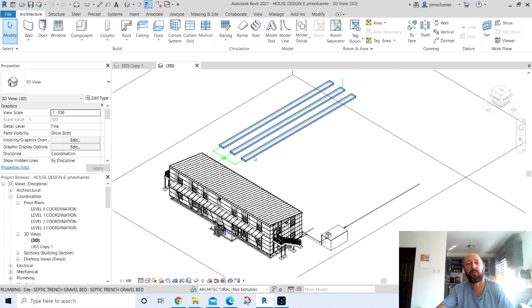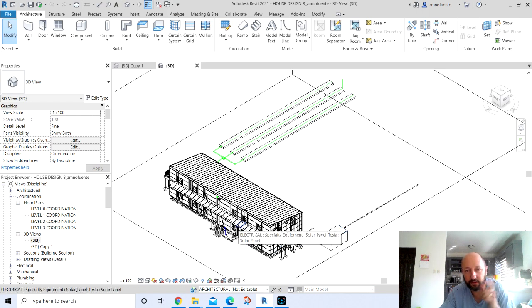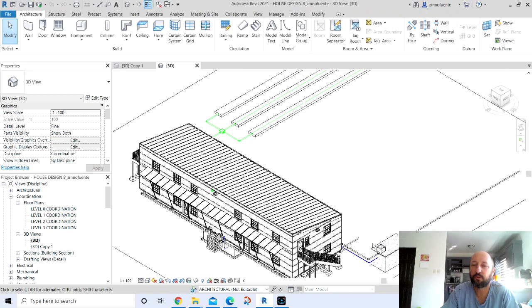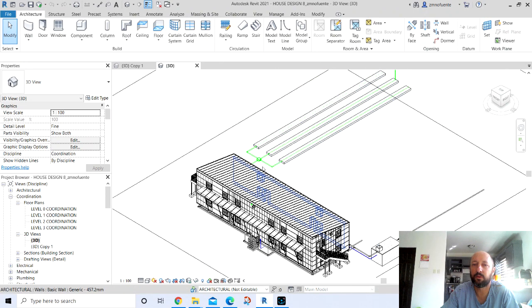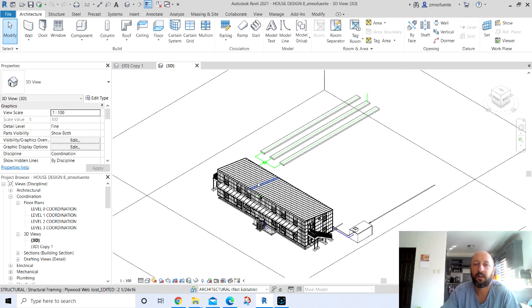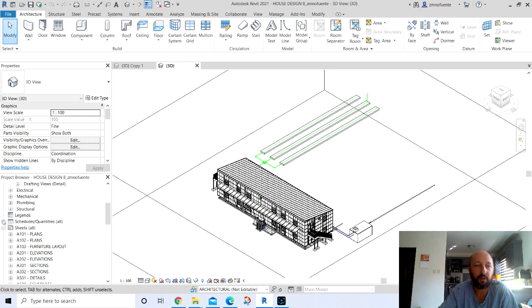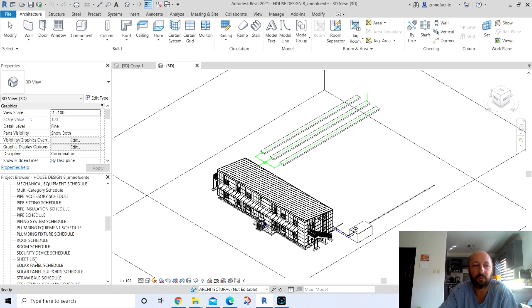Okay, so what I've got up here now is the Revit model. I used Autodesk Revit to create a 3D model for designing this house. Thanks Autodesk, great software by the way. One of the benefits with Revit, and probably other software as well, is that at the end of the day you can end up with a takeoff of all your material by using the schedules over here.